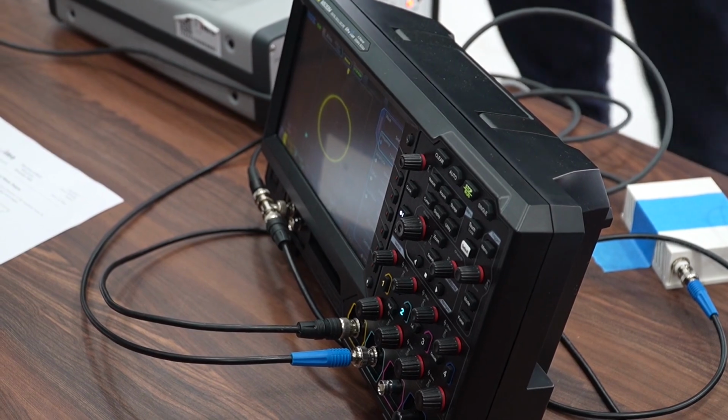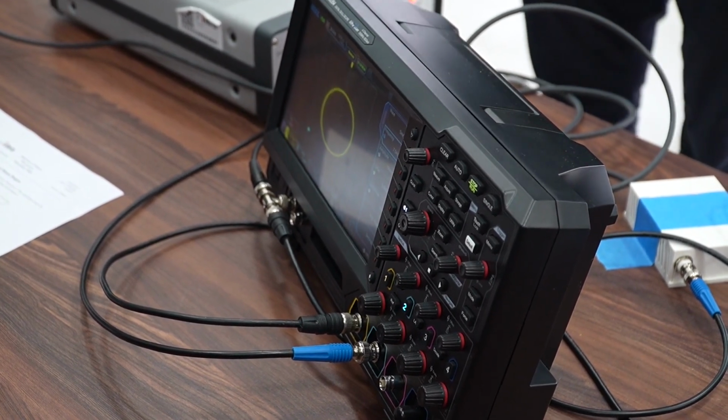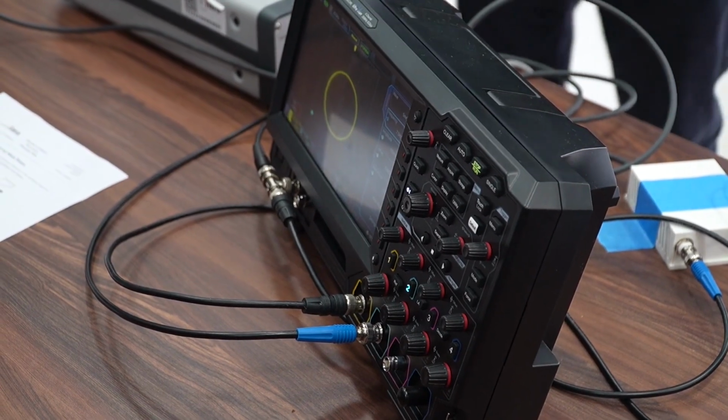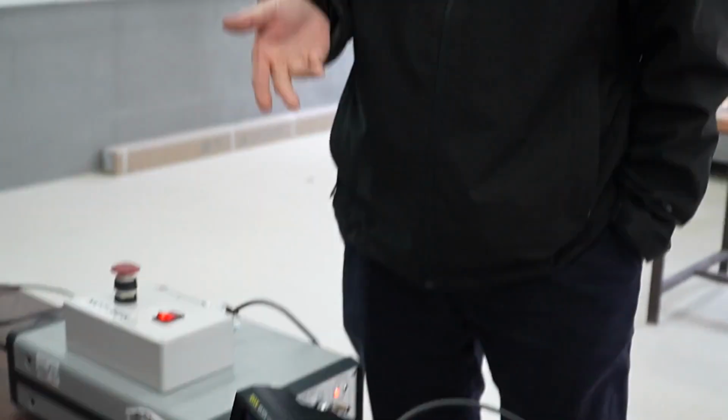Yeah. And this is actually because the angle between excitation and deflection should always be like 45 degrees, minus 45 degrees, and this is why you get the circle. So this is the reason behind it. Okay, so this is the first eigenfrequency, and now have a look for the second eigenfrequency.